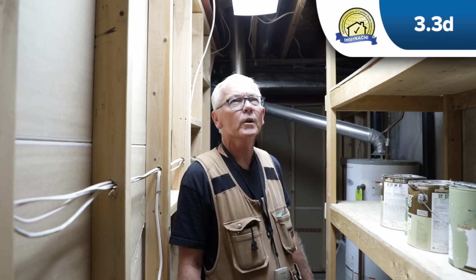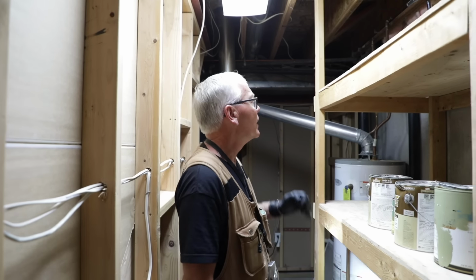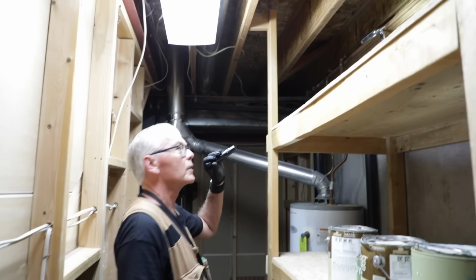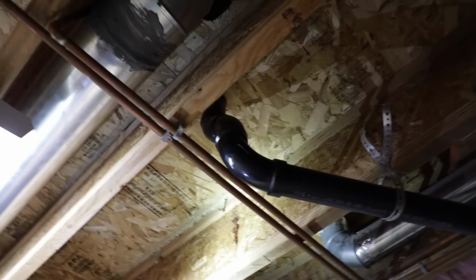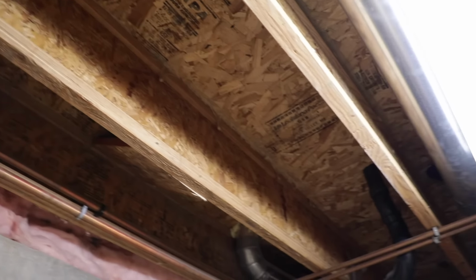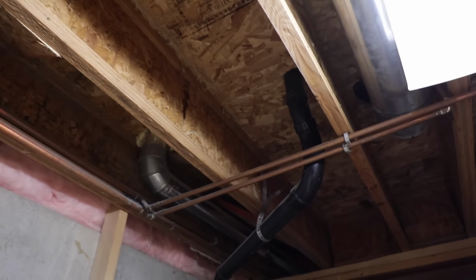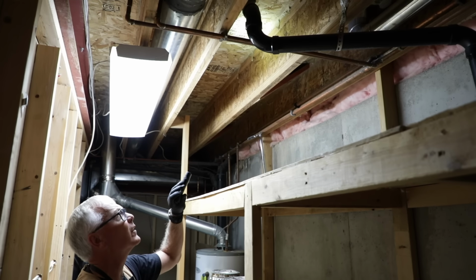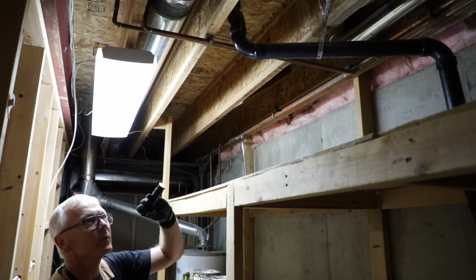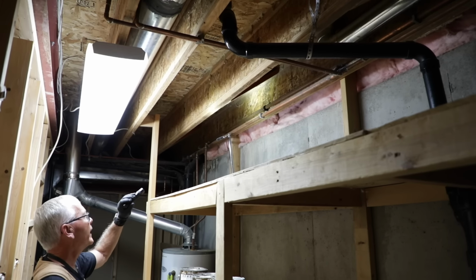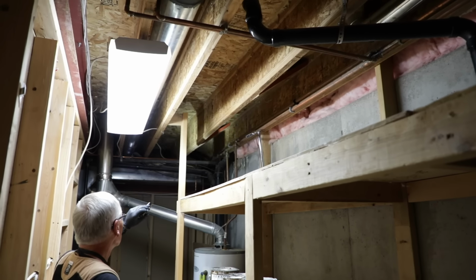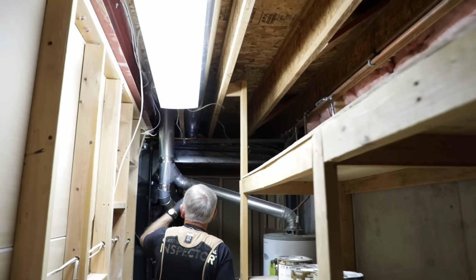Okay, now we're going to do the structural components, and we're going to start in this little unfinished area in the basement, since this is the only spot we can view any of the flooring structure components. And I can see that we've got some plywood TJIs as our floor joists. The decking or the subfloor is an OSB material. I'm just going to look for any bowing or cracking of any of these components.